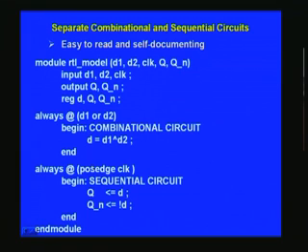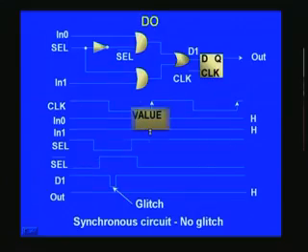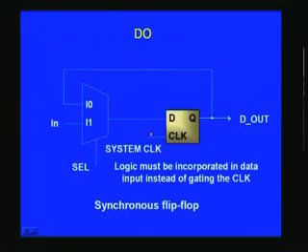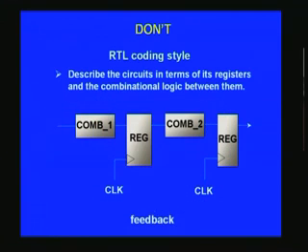Earlier we have seen how the basic RTL coding style will follow the pattern as depicted in this figure. First combinational, then register that, and then follow it by another combinational, register, and so on. This is how data flows as such. It flows from one point here, and then it flows to this, and then sets down here, and so on. It keeps on going stage after stage, and so it is the same pattern that we have followed in that particular code which we have.